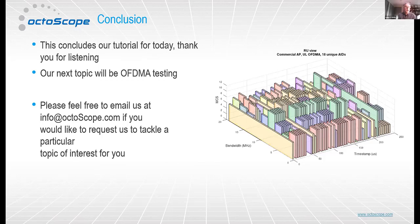And remember that the attenuator is not the only source of attenuation in the link. Again, we are an over-the-air testbed, so typically the link will contain an over-the-air link from the device under test to the test antennas. In the system we were just showing you, that attenuation was probably another 25 to 30 dB of loss. So we're talking about being able to get, even without anything else in the link, over 100 dB of attenuation.